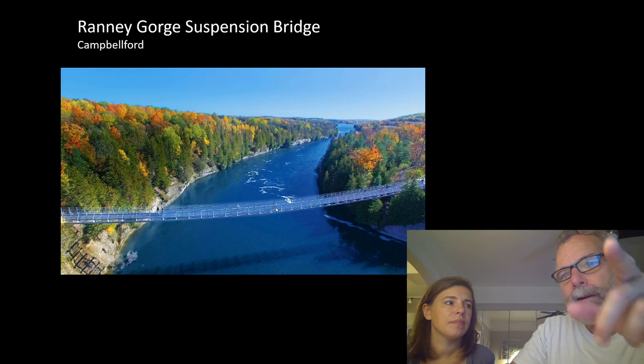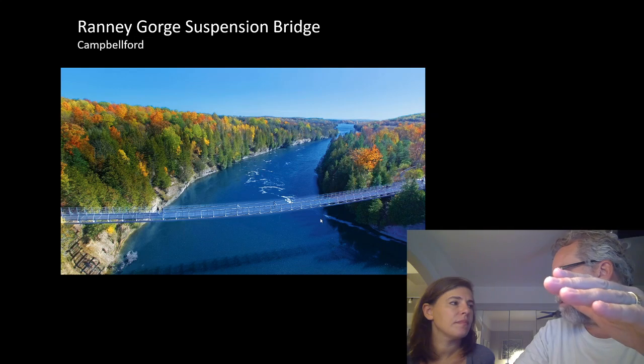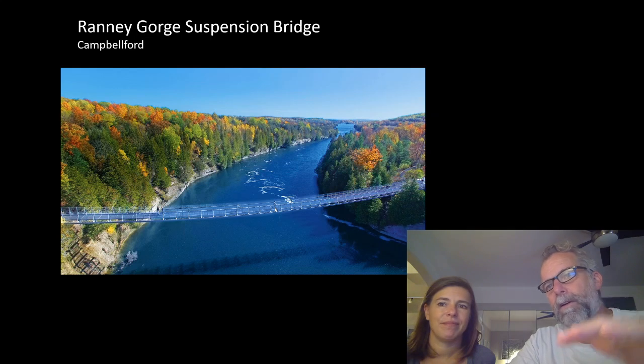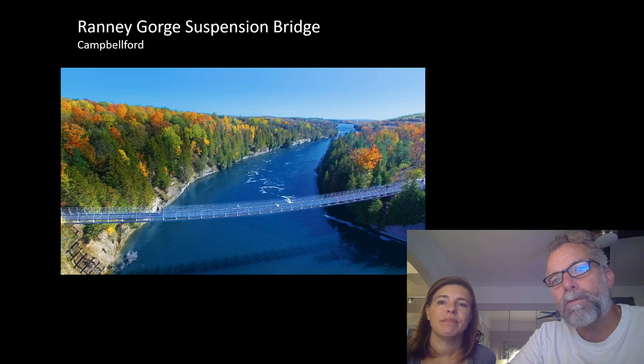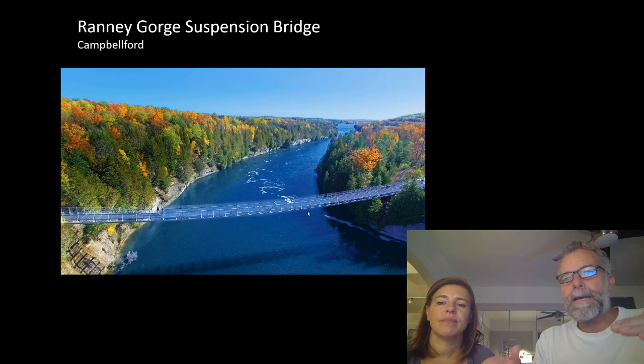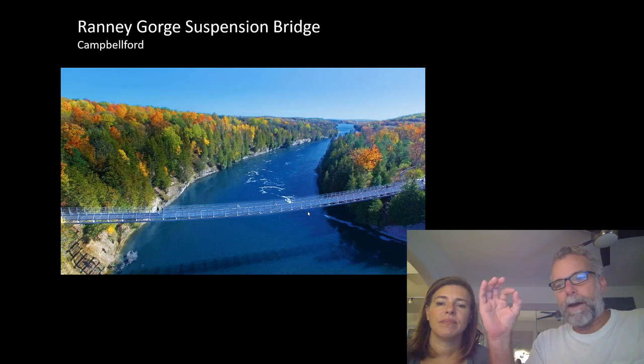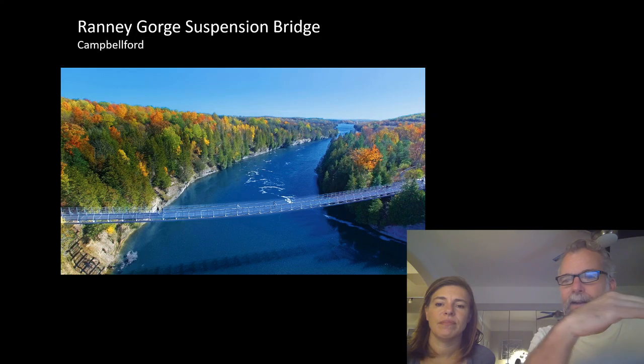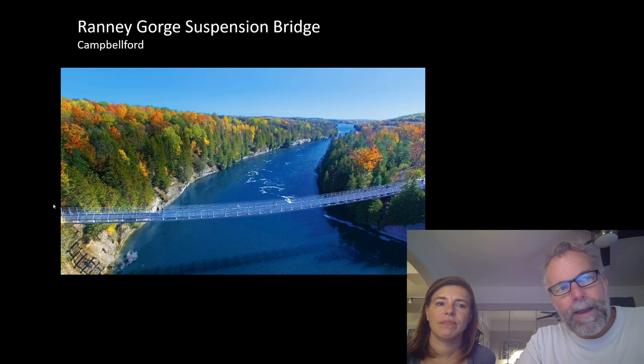The thing to bear in mind about a catenary bridge, this looks like a panacea, right? Like why wouldn't we just do this all the time? Very, very shallow, very long spans. The reason we don't do it all the time is that the abutment force is a function of the sag angle at the beginning. And if we have a very shallow sag angle, and let's assume it's 1 to 20